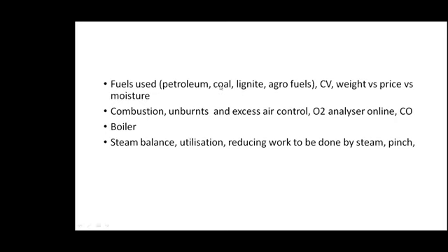So what we need to do is find out the cost per kilocalorie. Whichever is the cheapest, we choose that fuel. So it's not only about energy efficiency, but energy management. Ultimately, the industry is interested in reducing the cost. So we try to select the most economical fuel that will give us the requirements at the least cost. Besides the efficiency considerations, we also need to consider this.